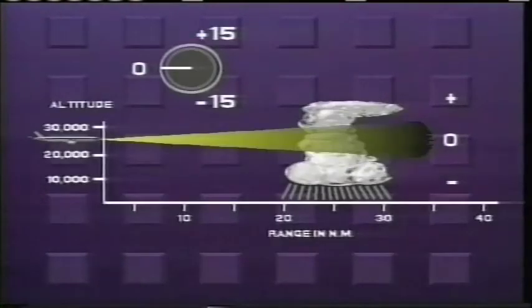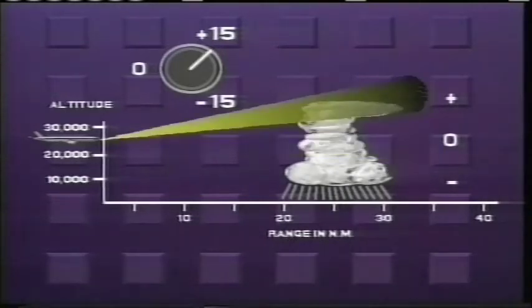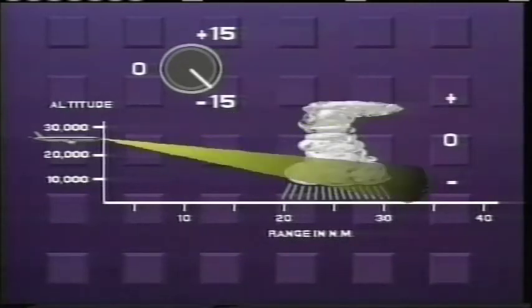The primary purpose of weather radar is to identify and avoid dangerous weather before you are in it. To that end, a radar operator must be able to adjust the elevation beam angle of the radar and know exactly where it is pointing. The antenna elevation pointing angle, commonly referred to as the tilt angle, can be manually adjusted 15 degrees above and below the horizontal plane, as was previously described. This capability allows the radar operator to point the beam of the radar at the thunderstorms at various altitudes.